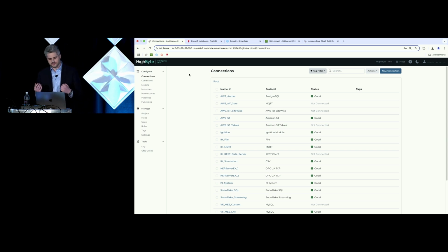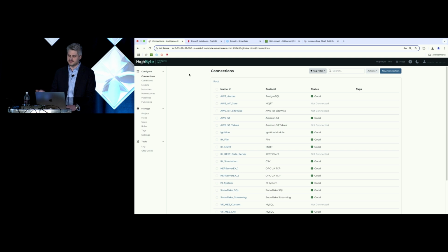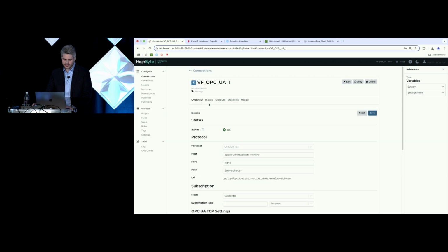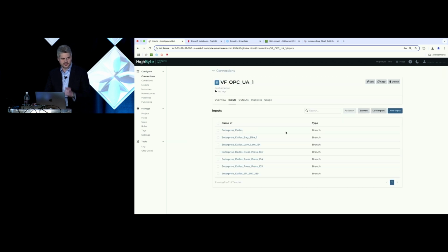And I think it's difficult if you haven't seen something before to envision what you want to do with it. So I think sometimes it is somewhat helpful to just first connect to data and aggregate it in one place. So this smart factory has an OPC-UA connection on there. I believe when I looked at the machines, they had Siemens Simotion devices. They actually speak an interesting variant of OPC Classic called XMLDA. So in practice, you'd probably be connecting these on here.